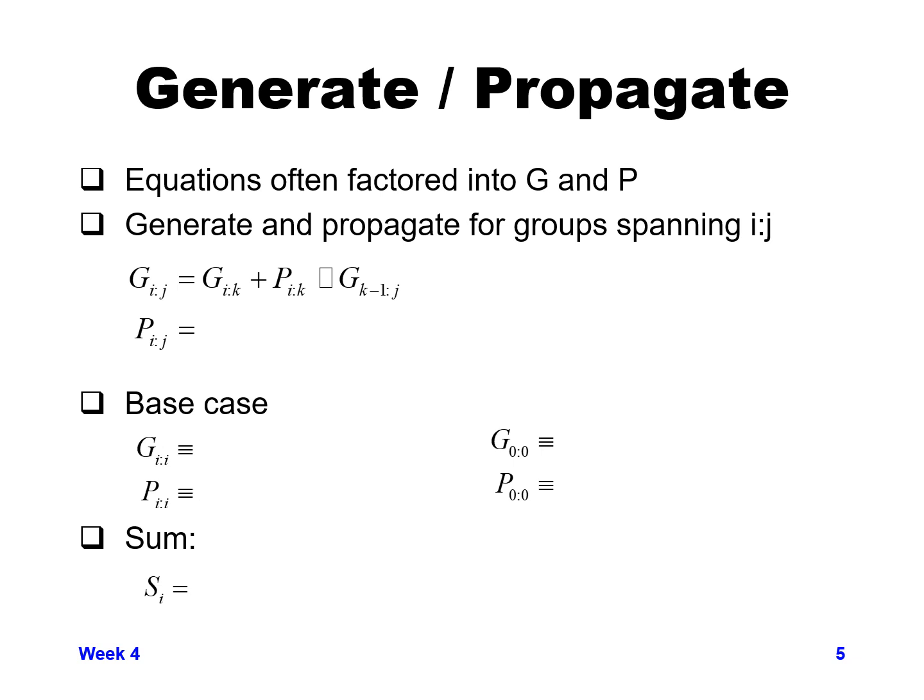Likewise, for propagate from 8 to 0, we can take the propagate value from 8 to 5 and AND it with the propagate value from 4 to 0. So we can now break this down, instead of waiting for something to propagate all the way through bit by bit, we can calculate these values on chunks of, let's say, 4 bits at a time, and use the combination of those 4 bits to do just a single function to get the overall 8 bits.